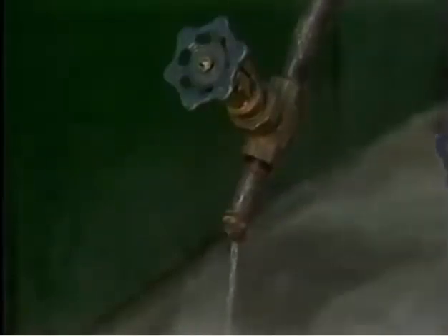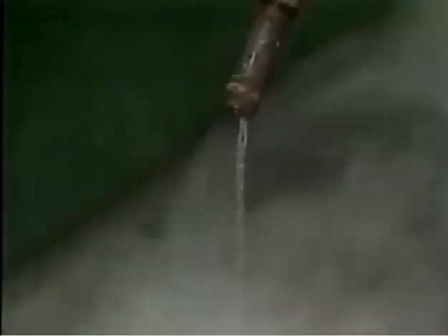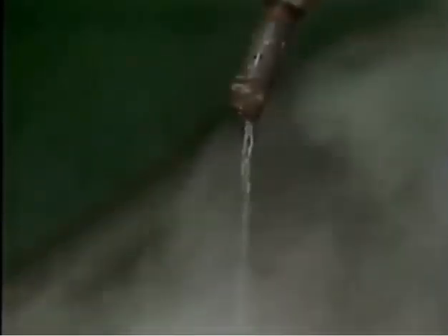Initially, condensate was removed by simply cracking a valve, wasting the hot condensate and some steam as well to the atmosphere. The next step in condensate removal was the application of an orifice plate. These plates were simply discs drilled with a fixed hole or orifice. They were inserted at the steam line drip point or equipment discharge line, draining condensate and venting non-condensables from the steam space.